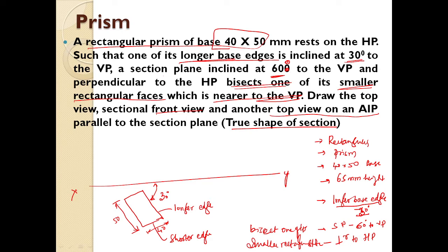Before drawing the front view, let us mark all these longer edges which are going to connect the top surface and the bottom surface. Right? For the top surface and bottom surface to connect, a longer edge comes, and I marked that. Now let us draw the lines from the reference points to the XY line.